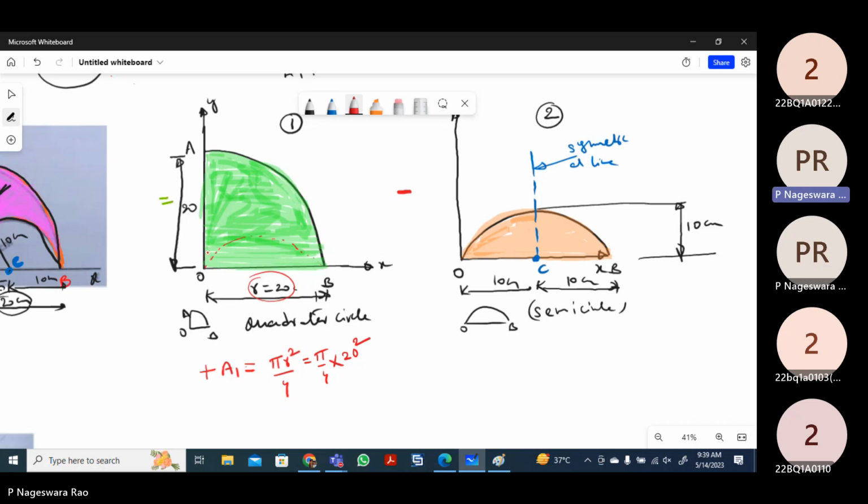Now, for the quarter circle, this is 90 degrees, where the origin lies here by default. So the centroid for this first quarter circle will be somewhere here. As per the quarter circle formula, from the y-axis it will be equal to 4r by 3 pi. As per the standard formula, this distance is also 4r by 3 pi for a quarter circle of 90 degrees. That means this is x1 and this is y1. Both lie in the first quadrant, hence they are positive only.